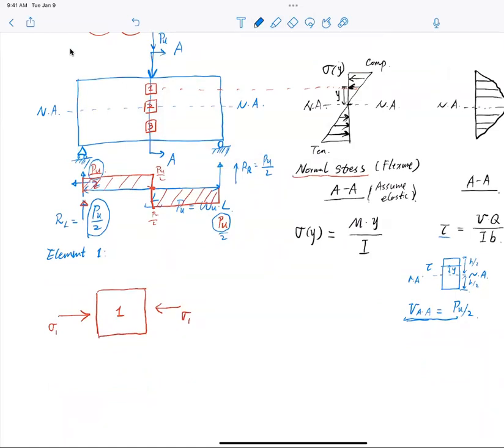Now, look at V, we have V, so that is fine. Let's look at the bottom first. b is the width of the section since I have a rectangular section, so naturally this is my b, and that is checked. We know that dimension. So what about I? I is the moment of inertia for a rectangular beam.